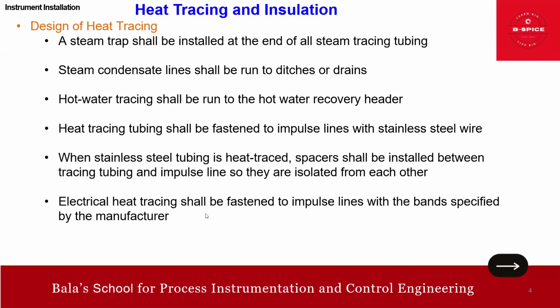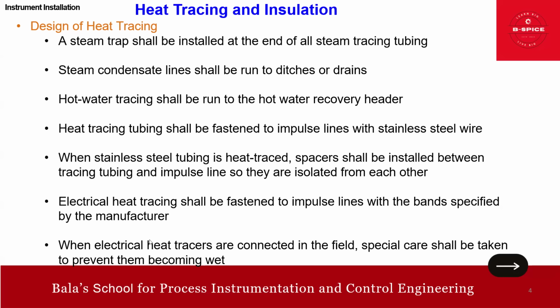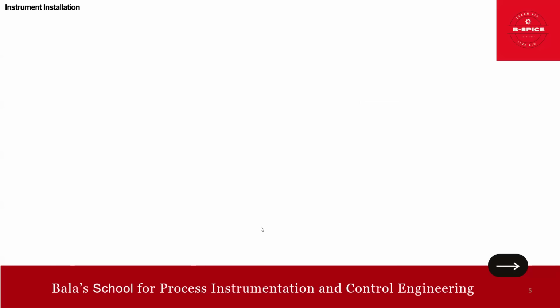Electrical heat tracing shall be fastened to impulse line with band specified by the manufacturer. Just remember that. These are some of the aspects we should take note of while doing the heat tracing. When electrical heat tracers are connected in the field, special care must be taken to prevent them becoming wet. Otherwise, it can cause shock. Okay, good. This is about the heat tracing design aspects.